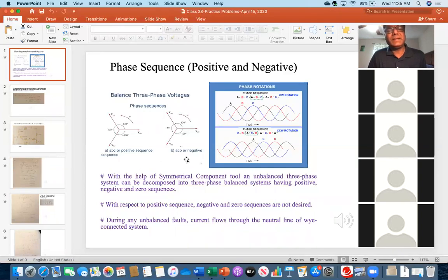In other countries, it is 230 volts. So if you have a 120 volt device and try to connect to their system, that will cause problems. Similarly, in United States, frequency is 60 hertz, but in Europe and in Asian countries, they have 50 hertz. Now, if you try to connect two devices that have different frequency, even if the voltage might be the same, still there will be an issue.